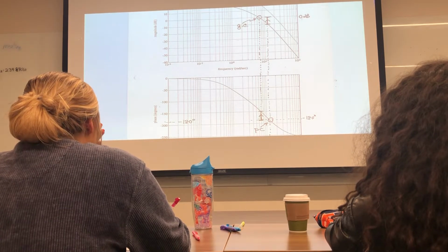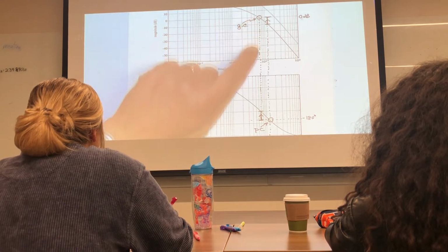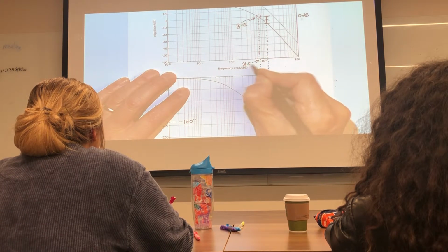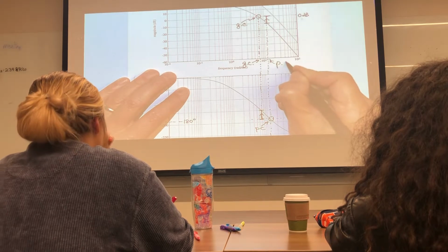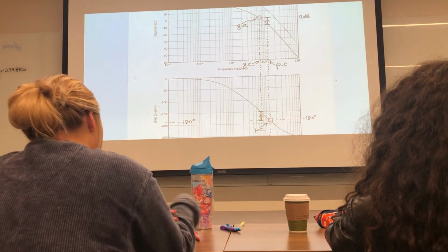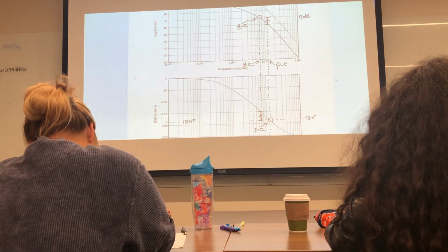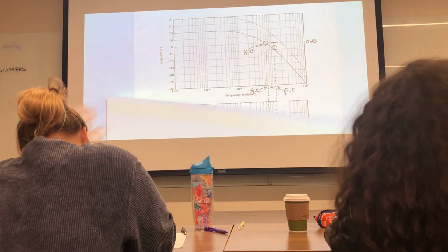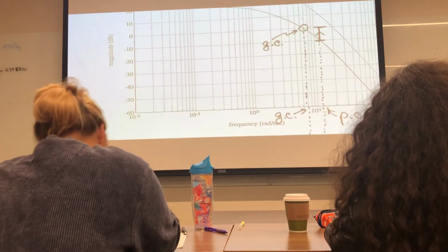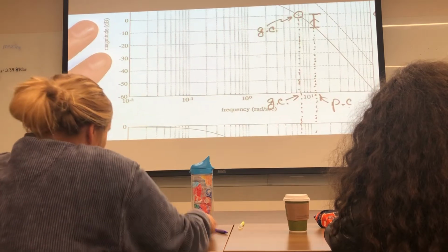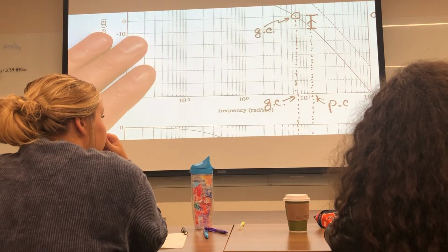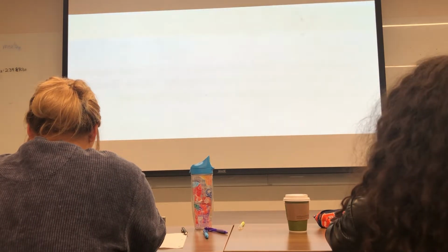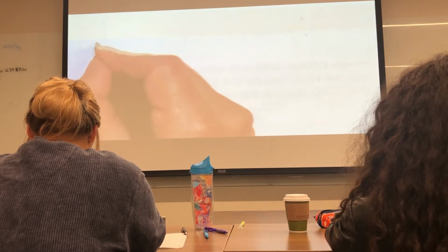Now, I'd like you to make an observation. Notice where the gain crossover is. We've got two vertical lines. This one is the gain crossover, and this one is the phase crossover. So one of the takeaways that control systems engineers know is that they can look at a Bode plot real quickly and determine whether or not the control system is stable. They don't have to sketch the Nyquist plot like we just did. So here's a tidbit, a conclusion.